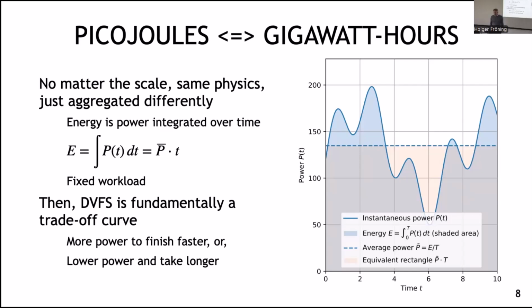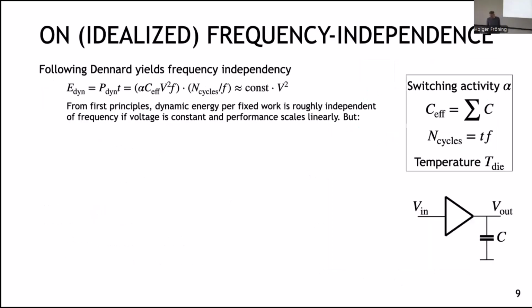So you vary your frequency and voltage settings and hope that you get somehow a little bit more energy efficient than before. And I actually had some rather involved discussions with many manufacturers, with the main message that they all told me, you can do this, but in our experiments, it never works out. Race to idle is your favorite game to play in this setting. So simply run things at high frequencies. And I was a little bit like, it doesn't make sense. Because if I remember my background education, then in principle, what we're doing in CMOS, what consumes most part of the energy overall, is actually charging capacitors. So we basically always have these transitions from 0 to 1 and back again and all these things.